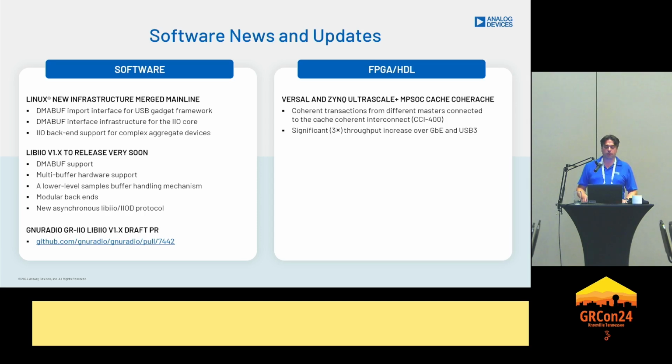The other thing I wanted to talk about, which I found really interesting, is the cache coherent transactions, or the cache coherent interconnect, on some of the newer SoCs, the ARM quad-core SoC types. They really boost performance. While we benchmarked libIO and the new protocol, we figured out that we spent the majority of the time not in the drivers, not in the library, not in user space. We spent it in cache management.